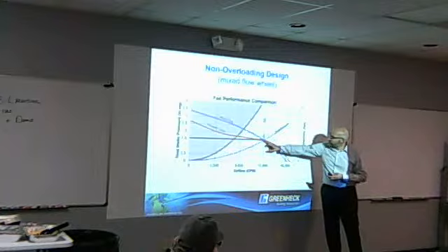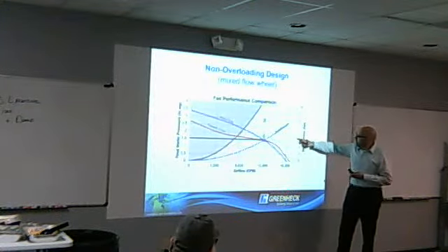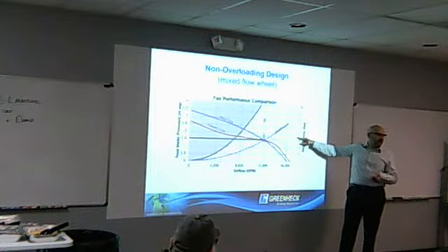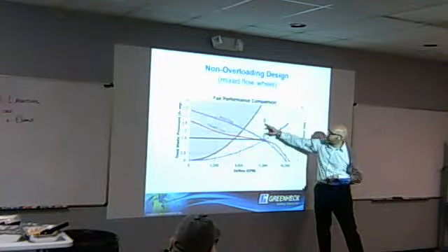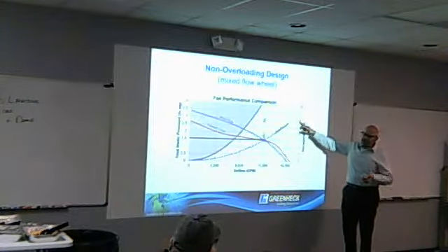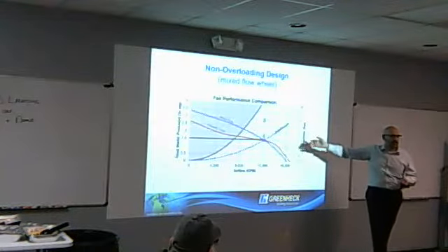So reading up from the system curve to the mixed flow wheel, the brake horsepower is, we'll call it 5.5 for our discussion purposes. The forward curve wheel has a brake horsepower closer to, let's say, 7.75 for round numbers, let's just call it that.